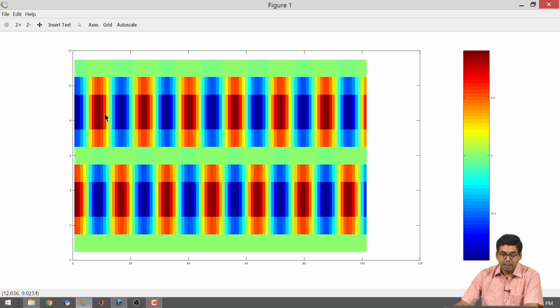Now, it means that in your waveguide, in the center of the waveguide, your electric field value has become 0, and there are 2 spots, all right, and there are some distinctions that we can also see. For example, one spot is having a value of say +1 electric field. At the same waveguide, the other spot is having -1, right.